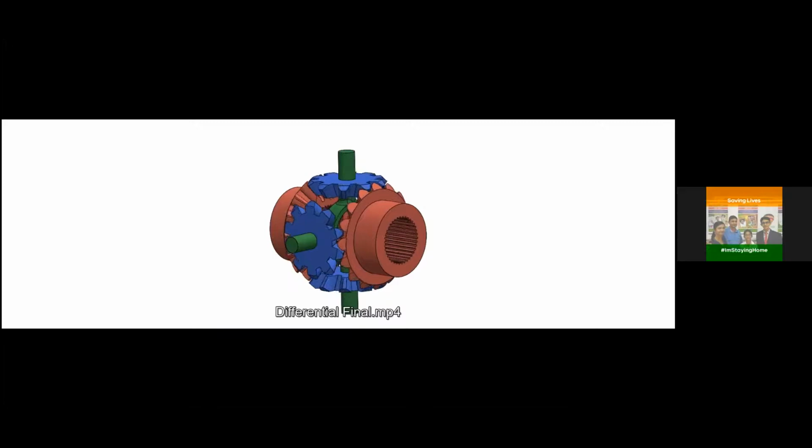Okay, great. So it means that there is no interference or collision between parts. The entry and exit of the teeth with respect to two different gears are very smooth, and you have done a very great job of doing all the modeling and motion study. And the best part was the parameterization of the variables, so you can anytime change the values of those variables directly from the list available to you, and you have all the different gears, the size of gears, the number of teeth, and you are done with the newer assembly also.